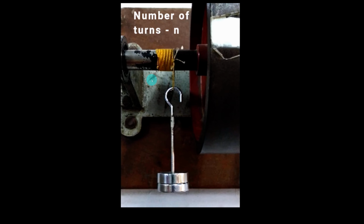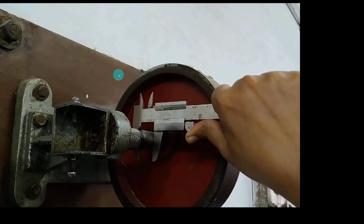2 pi r is one round, right? So if you make 50 rounds or 40 rounds, for example, then it is 40 into 2 pi r. For that 2 pi r, I need the radius, right? For that you take a vernier caliper and do the measurement. That is the part that you will be doing in actual practice, when you are doing it in the lab.